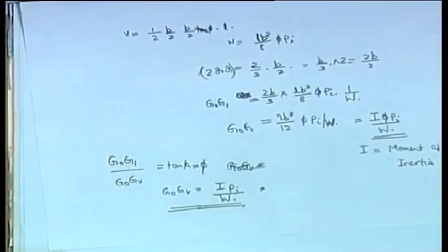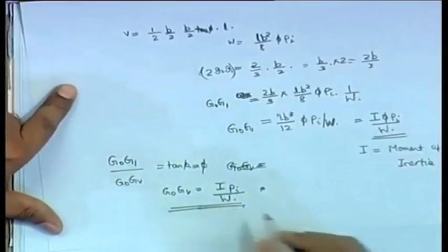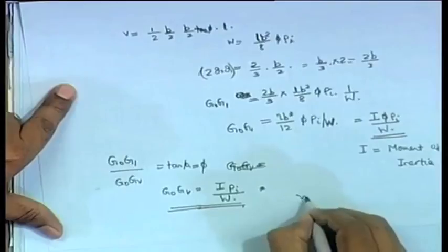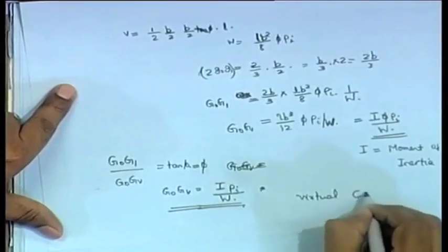So, why is it called Gv? It is called Gv because it is called a virtual center of gravity. When the ship is inclining like this and the free surface is moving up and down like this, because of this the water inside the tank is moving up and down. Because of that, the center of gravity of this is going up and down. When that is happening, the center of gravity of the ship also goes up and down. So, that movement can actually be represented by this Gv.